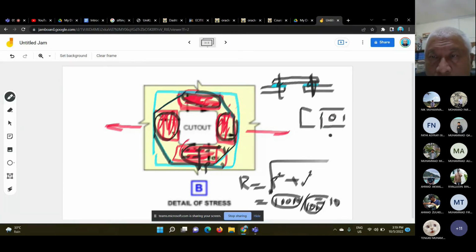That's why you can see a lot of holes in aircraft design, cut like lightening holes. So we can do that if the repair is big, yes. If the repair is small, not necessary. However, if the area is critical for fatigue, we may also do this taper because we do not want to drill too many holes on the structure, because too many holes will reduce the fatigue life of the structure. Questions?